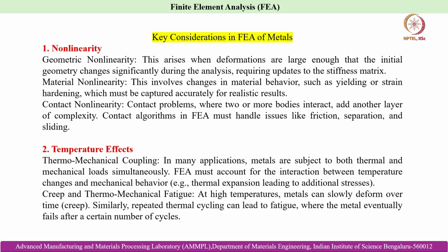So, what is the contact nonlinearity? Two or more bodies interact, so there can be friction, there can be separation, there can be sliding of one body past another body. So, this is the reason for which nonlinearity arises in case of contact problems.